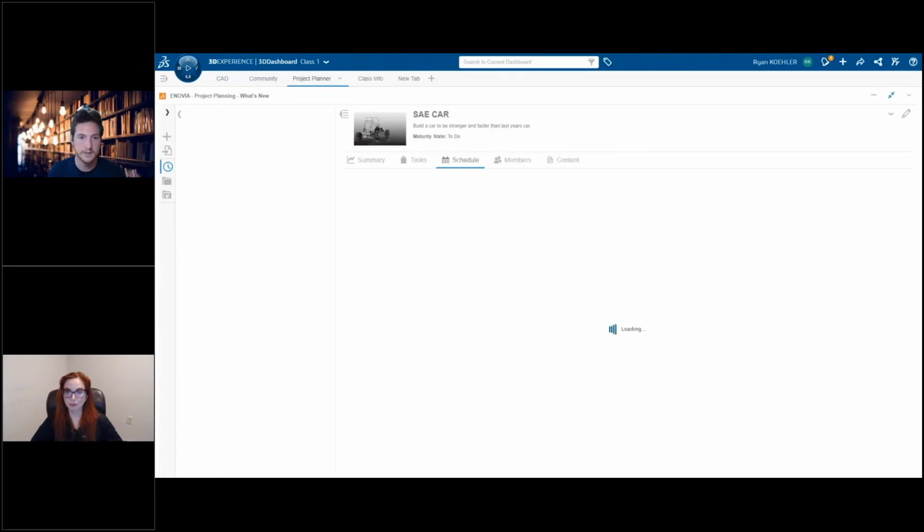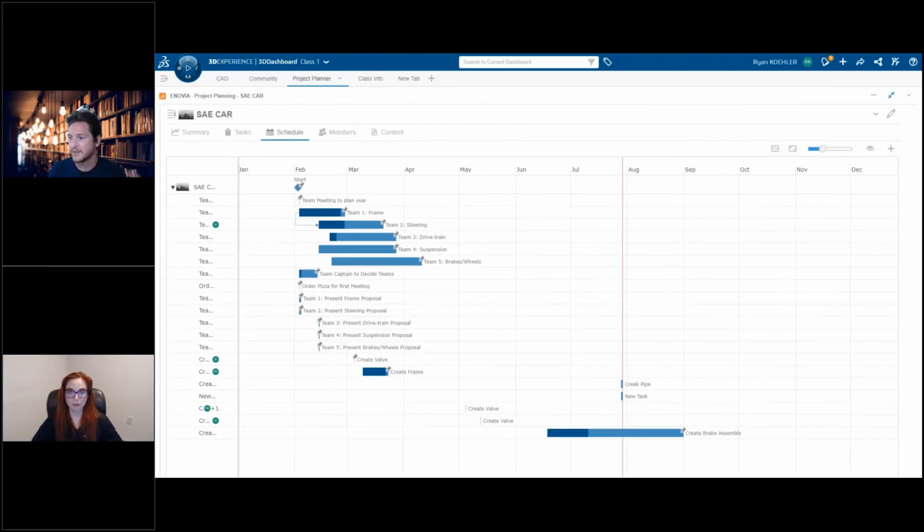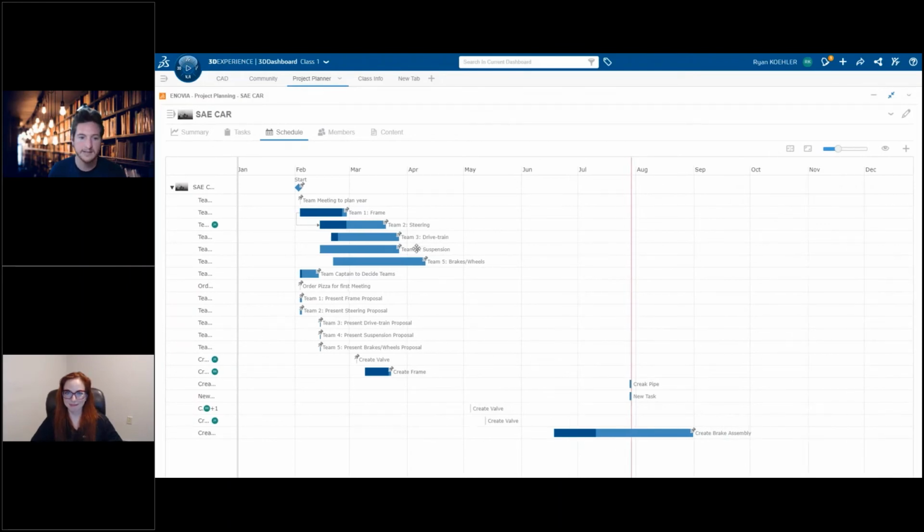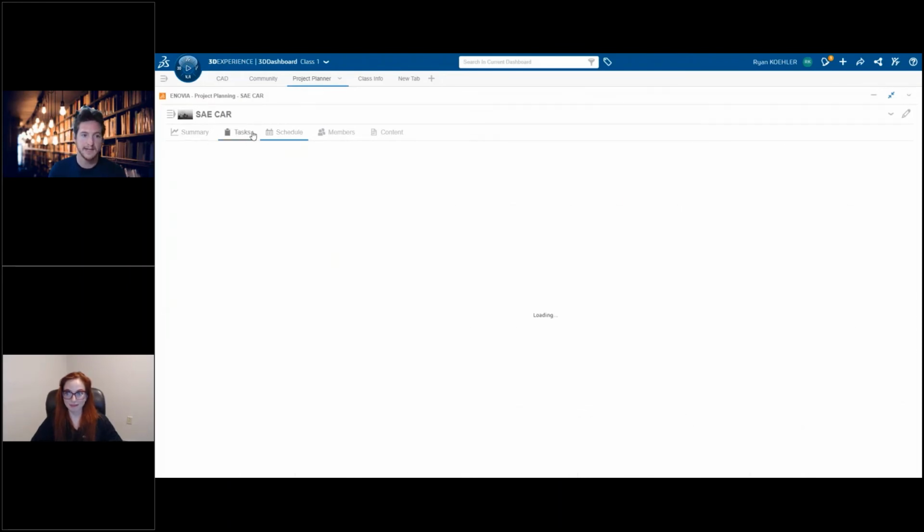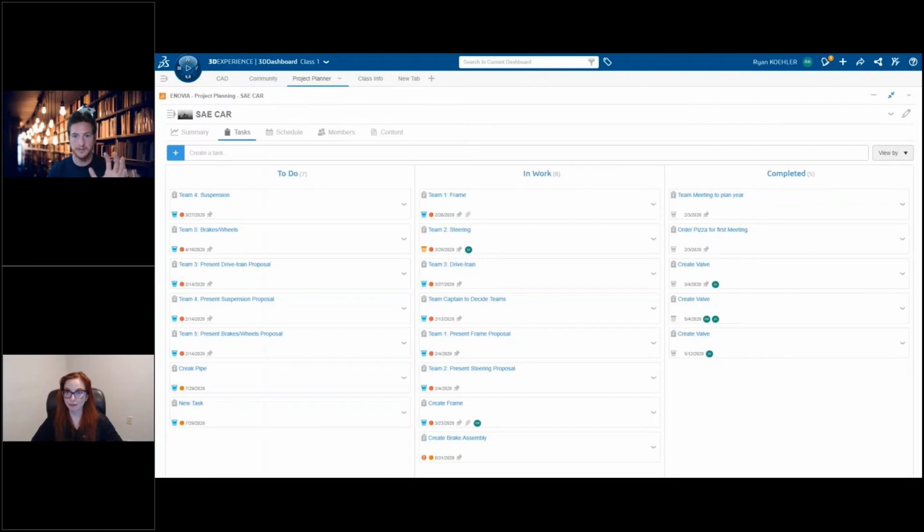That's a great question, and the question there is, can the blob be combined with the solid? It actually will mesh what I just showed you inside XDesign and XShape. That blob will actually mesh into the same surface as the cube. And basically, I can go back to XDesign and trim away a section using an extrude if I want to. So they actually perfectly combine together.